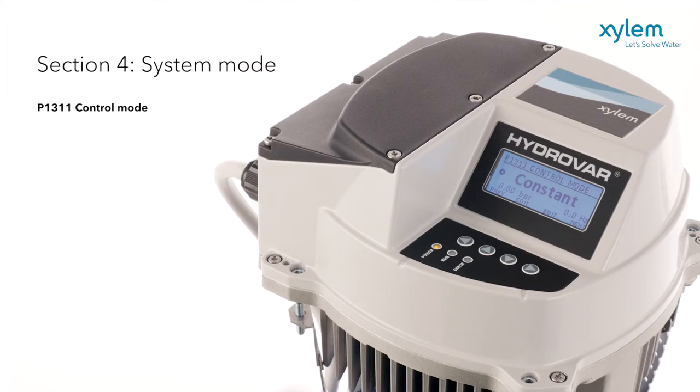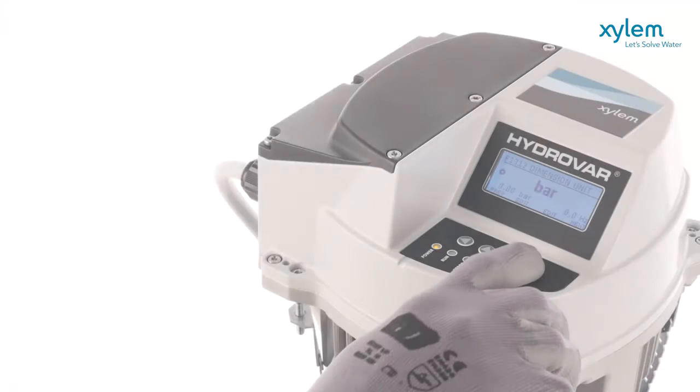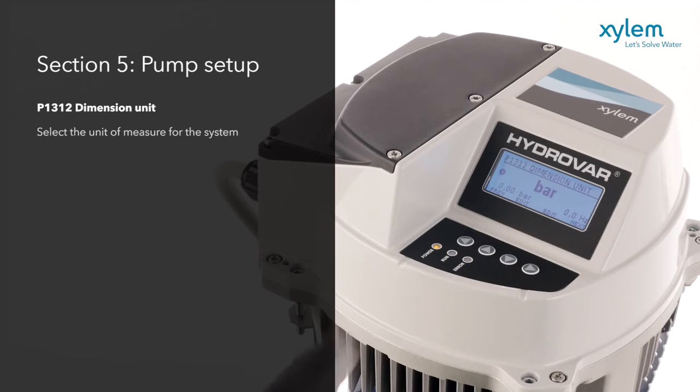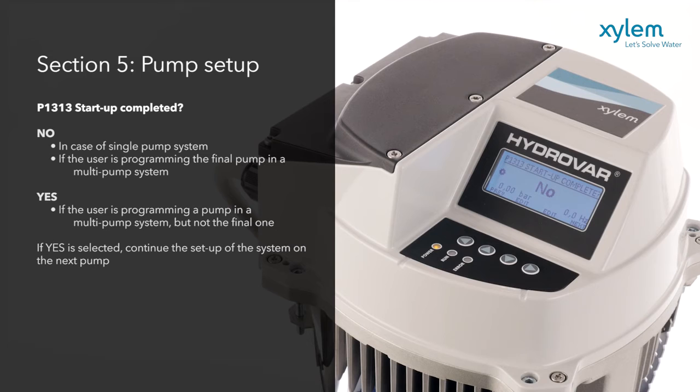Follow a system curve and control the pump according to an external signal. Then set the unit of measurement for the system. In a multiple pump system, the procedure can be stopped at this point on all pumps except the final one by selecting Yes, and then completing the procedure on that final pump by selecting No.